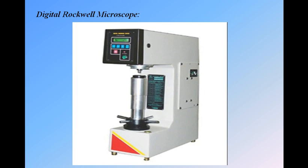Okay, then this is a digital type. See here, this is a screen where we finally get the actual hardness value. Here you don't have to calculate anything, it gives you the direct value of hardness measurement. In the previous one you had some calculations. In this Rockwell hardness tester we don't have any calculations, it gives you the direct value of hardness. Just take what amount of load you want, that is 50 kg, 100 kg or 150 kg.